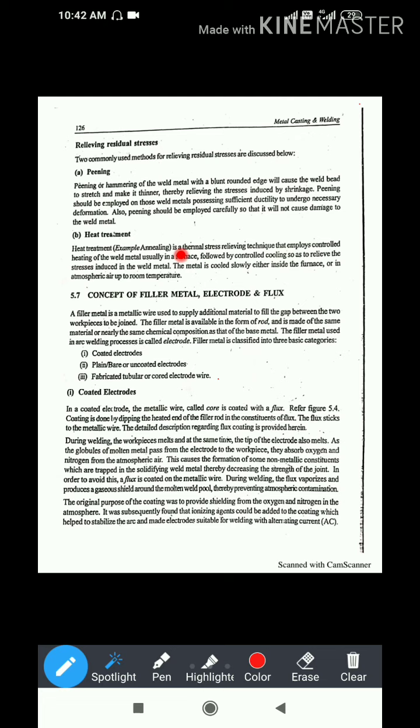If the weld material is deposited thick, make it thinner with the impact blow of a hammer. When it extends, the expansion of the weld material lets the residual stresses flow out. In this way the residual stresses come out due to the hammer impact and the expansion of the weld material.